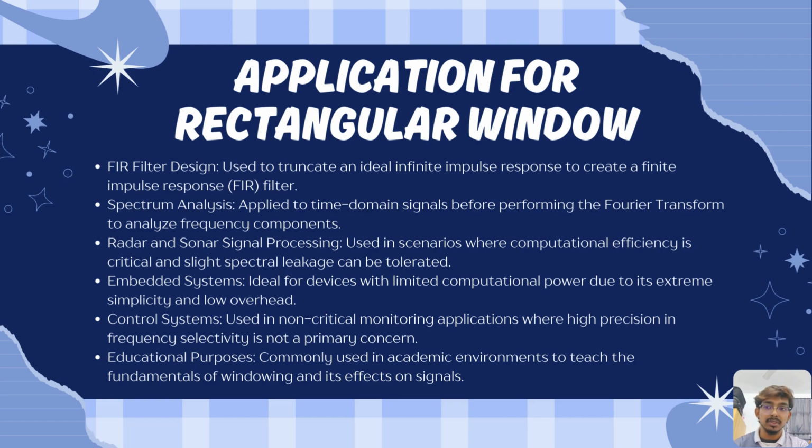Okay, last but not least, I want to talk about the applications for the rectangular window. We have listed out some applications. Firstly, FIR filter design, which is used to truncate an ideal infinite impulse response to create a finite impulse response, which for short we call an FIR filter.